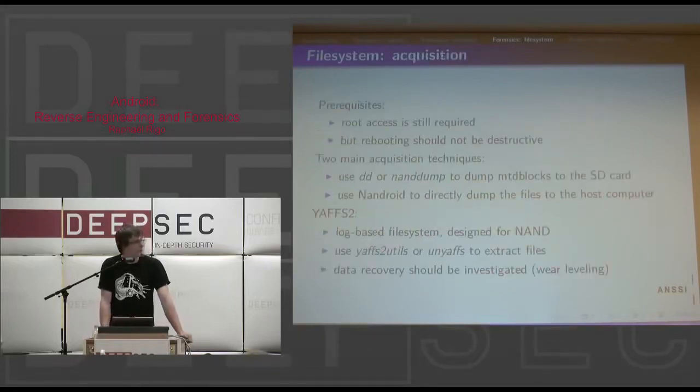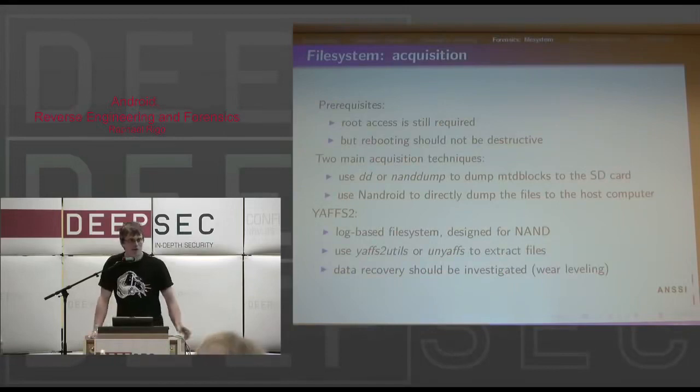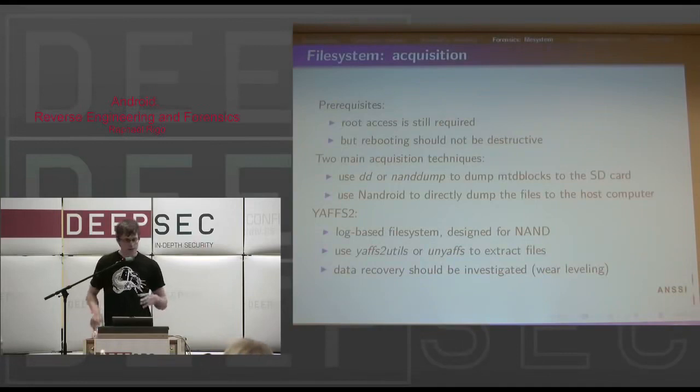I don't think so. I think these flash file systems, because erasing a block takes that long, usually use a background job to erase blocks, so it might not be much. Well, I've read the specification of the file system, and it could work. It depends really on the implementation, because unless you have the garbage collector running, the blocks shouldn't be erased. So I think it depends on how the file system is tuned. When does it trigger an erase because it's time consuming, and when does it stay as it is?